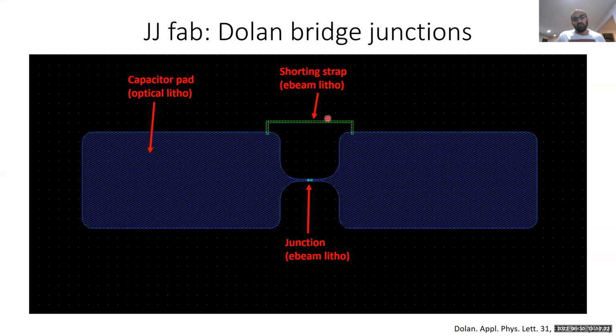But I do want to emphasize that you can accumulate ESD at sort of any step in your fab. Depending on how careful you are and how well grounded your equipment is, this can either be very effective or not really useful at all.